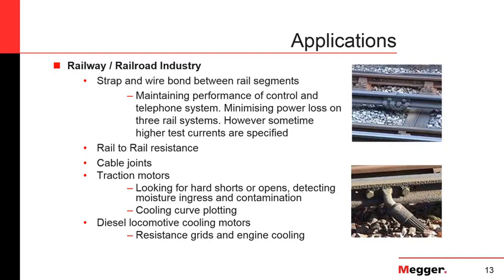When making measurements, the operator can select a 5-foot section of track without a bond, make a measurement, and then repeat the same procedure, but now taking another 5-foot section of the track with a bond in the middle. So a rule of thumb in this case will be that those two values should be within a few microhms. Usually, they should differ from each other by plus or minus 5%.